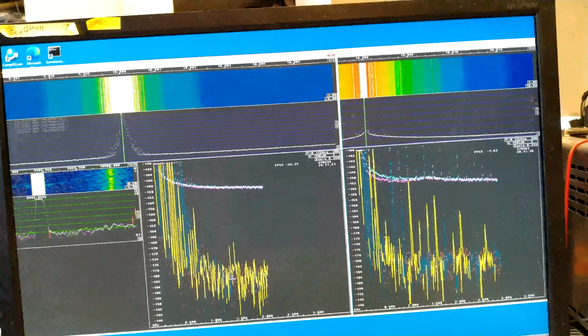I have increased the sampling rate of the sound card, the M-Track Quad, from 44.1 kilohertz to 96 kilohertz. And obviously the noise floor is much better now. It competes reasonably well with the SDR-IP. So I will wait for a while and look at the presence of spurs with negative sign.